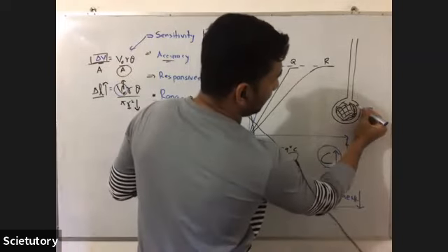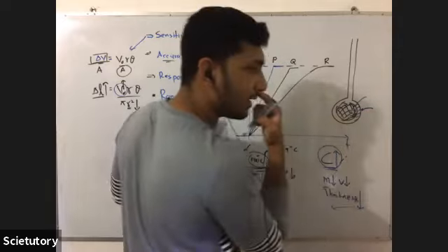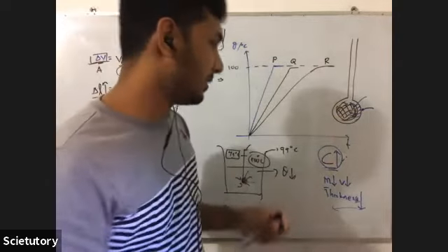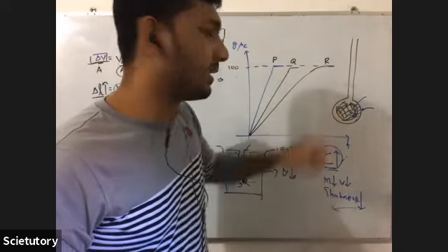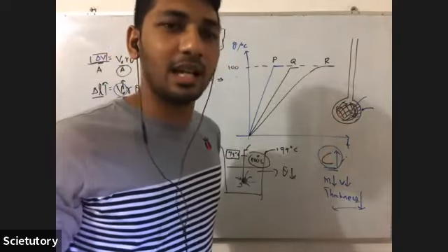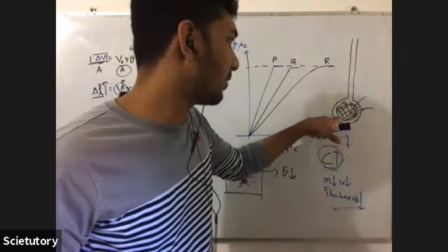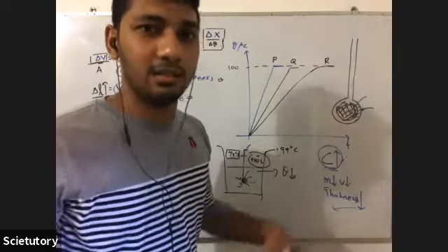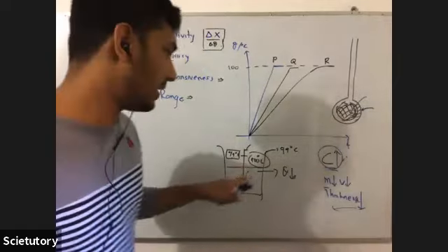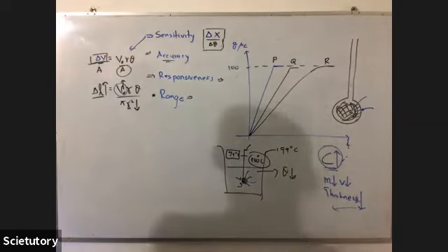So first this particular part of the thermometer will absorb heat, and then it will go to the mercury. So the amount of heat is determined by the thickness also, because if the thickness is high, the amount of the glass is also high. So you have to give some amount of heat to this and some amount of heat to this. So if they are high, the absorption of heat becomes significant, and that significantly reduces the temperature of the liquid.